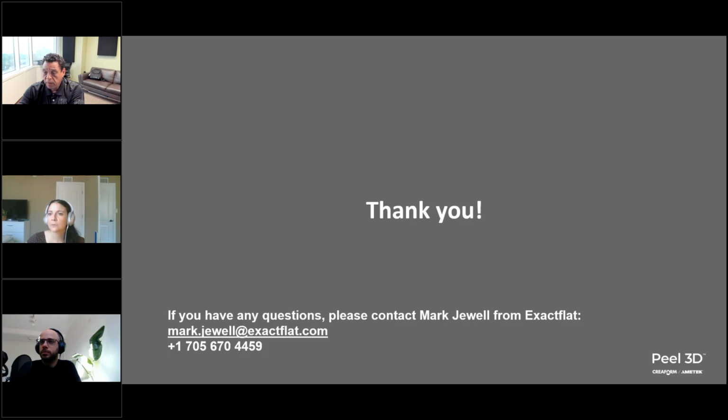Sure. So from Dustin, we have, for use in the marine canvas world, what's the total range for scanning? Say we had a top that is 14 feet long, 8 feet wide, 6 feet tall. Can we navigate around this with the scanner? You could potentially do this. You would have to make sure you'd be placing targets all over the part, since it is mostly flat and mostly large and wide. So these targets, you'd be placing them around like every 4 inches or so. So you could still do it. It would just take a long time to place those targets down.